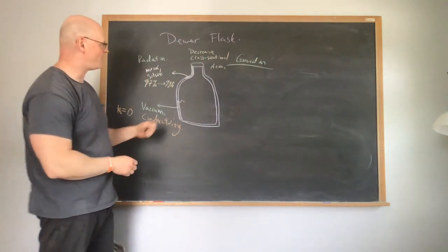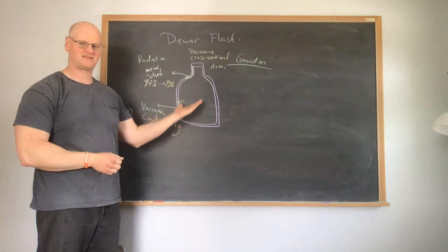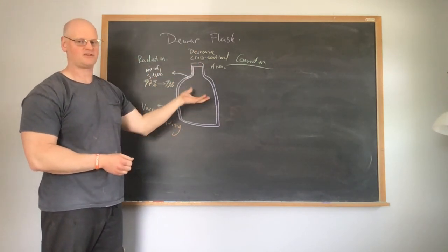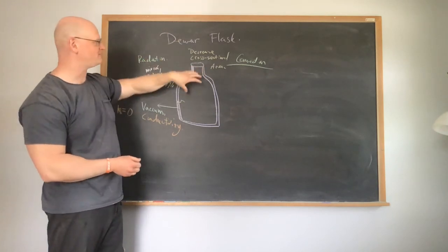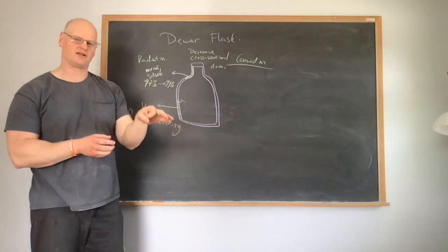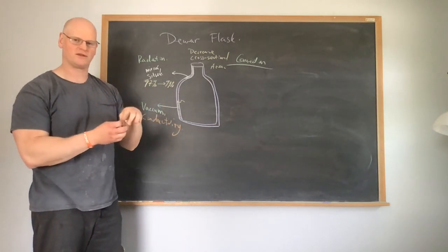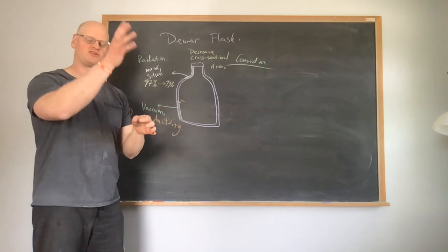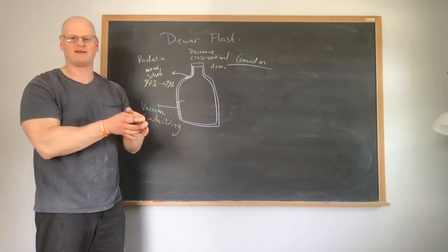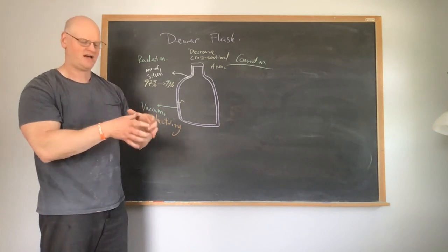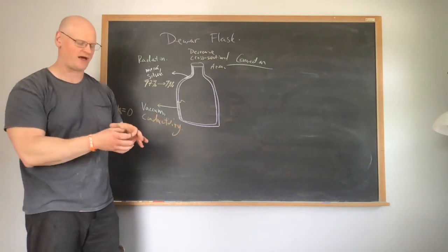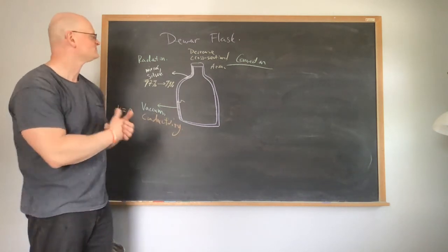So here, what happens is when you open up the lid, steam is going to come out, right? As the steam comes out, you're carrying away energy via the convection of the steam. So if you make the cross-sectional area as small as possible, or at least smaller, then the amount of steam you're letting come out, and the energy you're losing, is going to be at least somewhat minimal, right? As opposed to if I had a very large cross section, then I have a lot of steam coming out, carrying a lot of energy away.